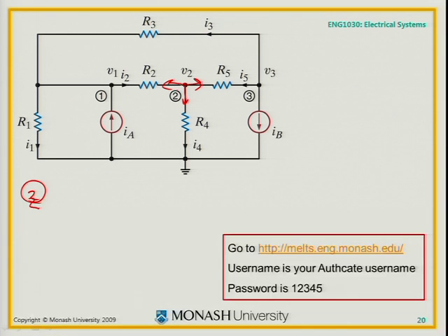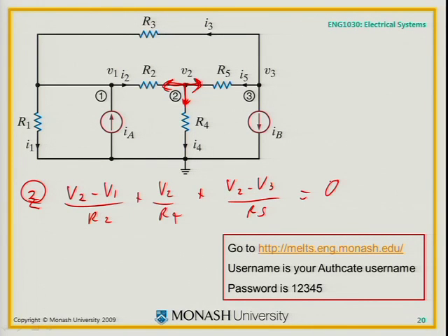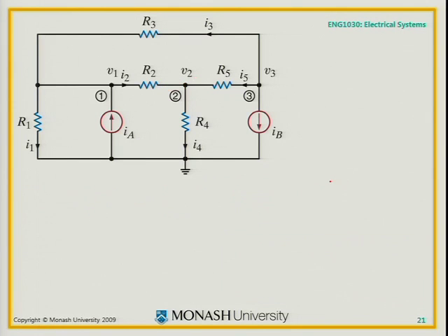We should have this current is V2 minus V1 on R2 plus V2 on R4, that's the one down there, plus this one, which is V2 minus V3 on R5 equals 0. That's the C. 75 out of 79 responses had that. It's, to me, a fairly good indication that you know what's going on here. Or you just guess, your good guesses could be it as well.